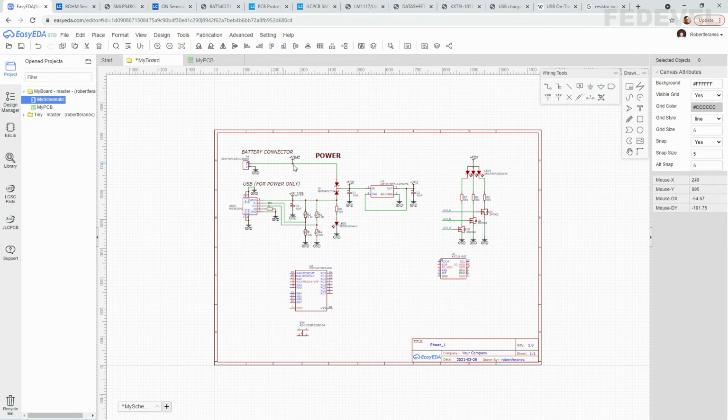the power goes through this diode. There will be some loss, like, I don't know, 0.5 volt. Then it also goes through these transistors. There may be some voltage loss across these transistors, but our calculation is still good enough to use the values of the resistor that we have calculated. The currents are not going to be higher.